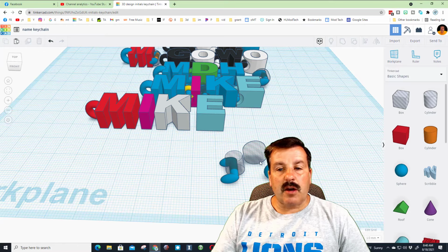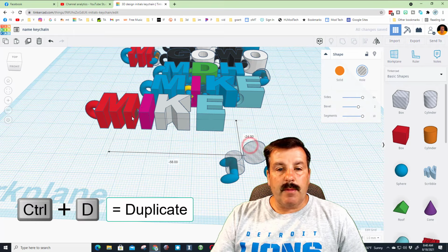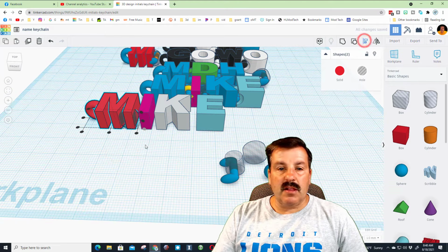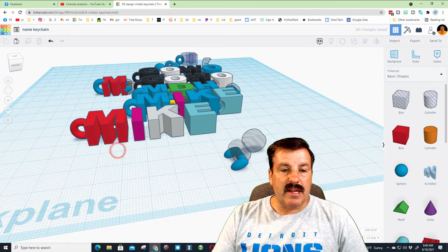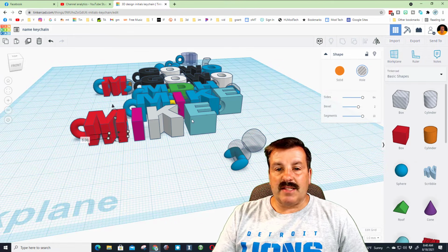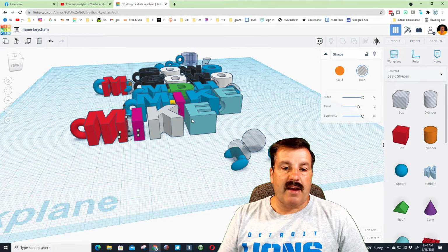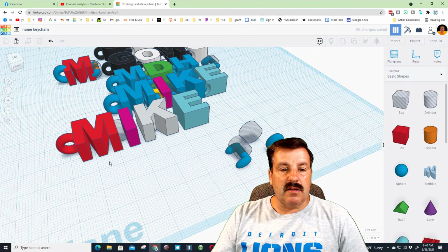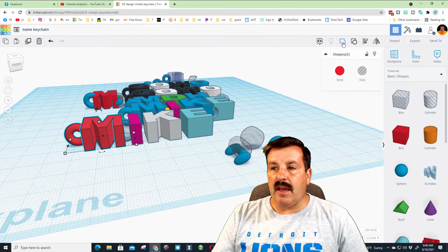The next step is to cut a hole in this end. We're going to do that with this piece. Once again, Control D. I'm going to drag it close. I'm going to select the 2 items. Click align, click on the red one, front edge, middle. So this is that part hiding inside here. Notice I've got it selected, and I want to push it out 5 clicks. 1, 2, 3, 4, 5. That is going to cut in the location so this ring doesn't get fused to our M. Let's select those 2 pieces and group them.